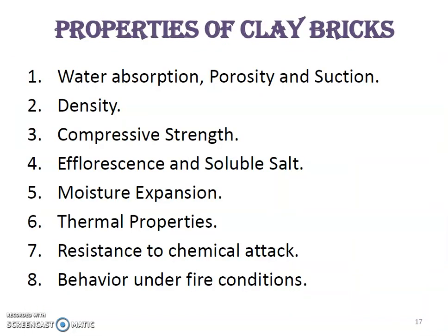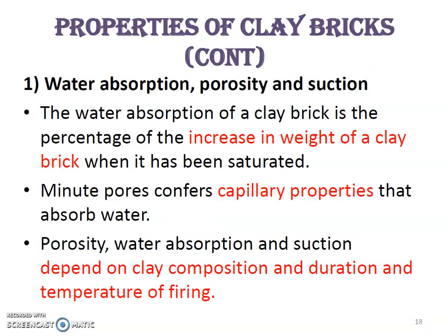Okay, properties of clay bricks, we have 8 properties. First is water absorption, porosity, and suction. These properties depend on the clay composition, duration, and also temperature of firing. How we measure the water absorption is by the percentage of the increase in weight of a clay brick when it has been saturated. So we weigh the initial clay brick and also after immersing in water for at least 24 hours. The difference in weight is considered as the water absorption percentage.